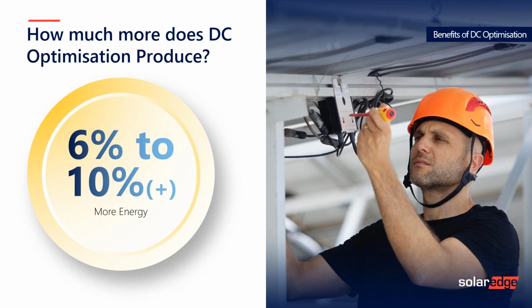But if we bring that back to, say, the ROI period of around 5 years on a 10 kilowatt system, that's $2,500 in extra savings that a homeowner would receive if they went SolarEdge. And that pretty well covers the delta that we see with many string systems today in the market. So it's a classic case: you pay a little bit more at the start, but you get a lot more over the life of the system.